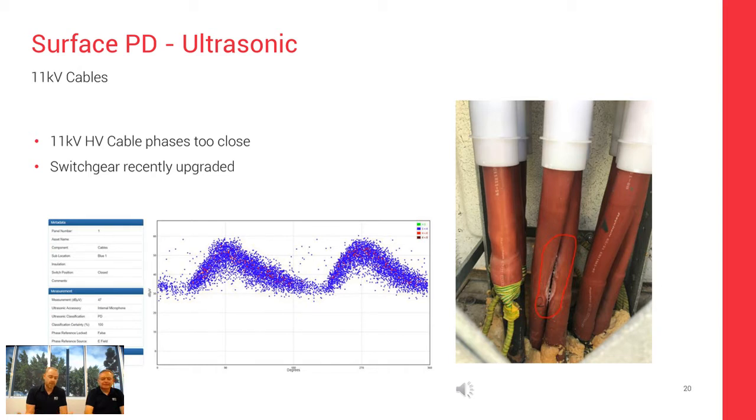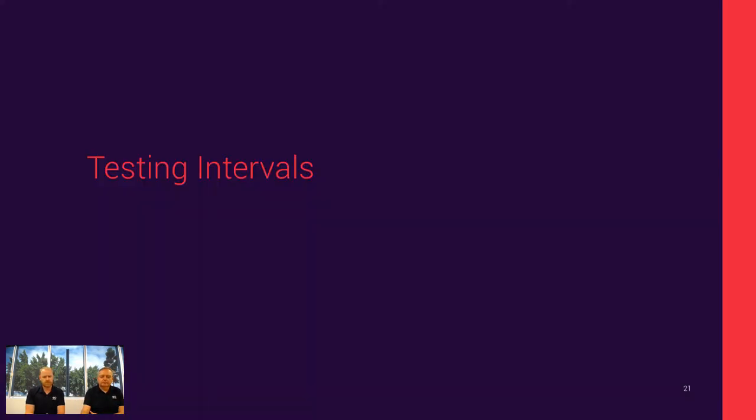We have found that one there was found visually, it was found with our own ears, but the instrument was also able to take a recording of it and help further diagnosis. The algorithm there predicted 100% certainty that the sound was being caused by partial discharge as well, so it gives further confidence, again, even though we can see it. So that's just another case study.